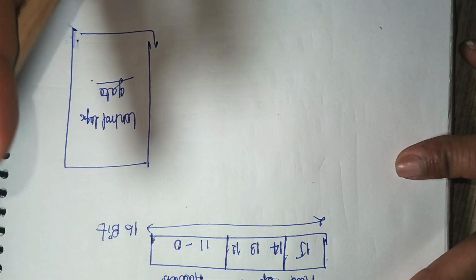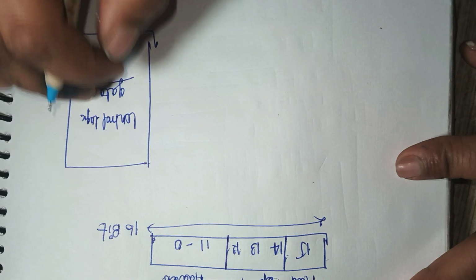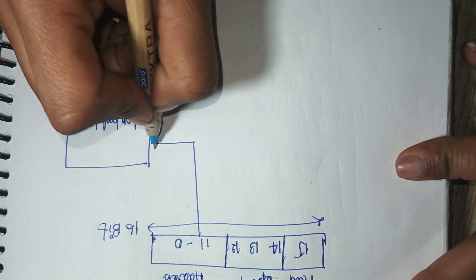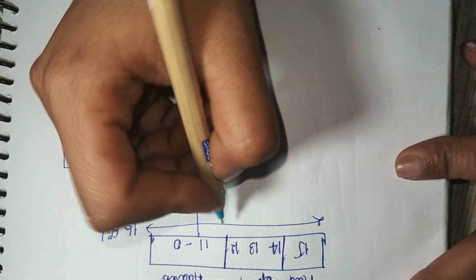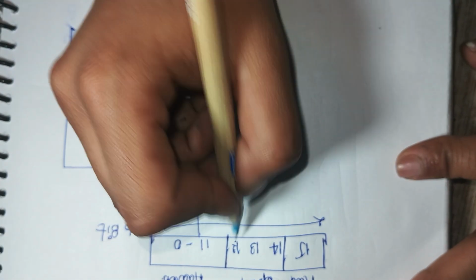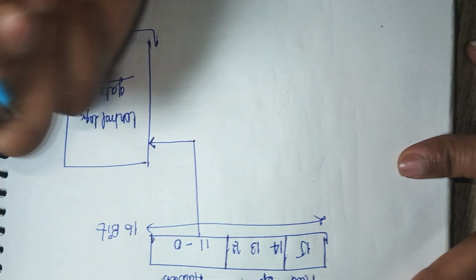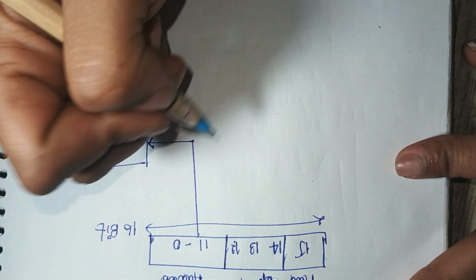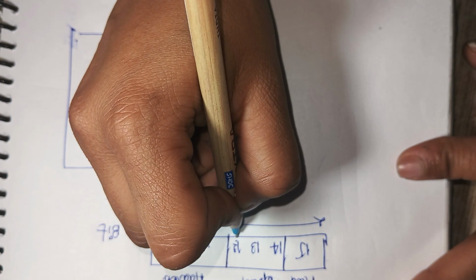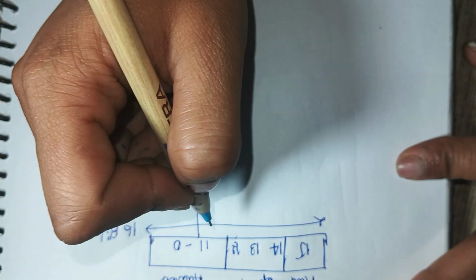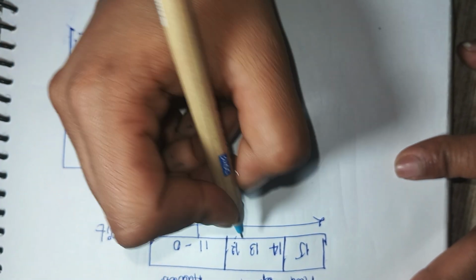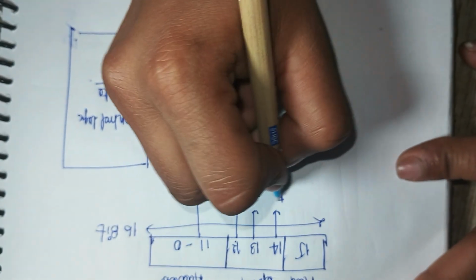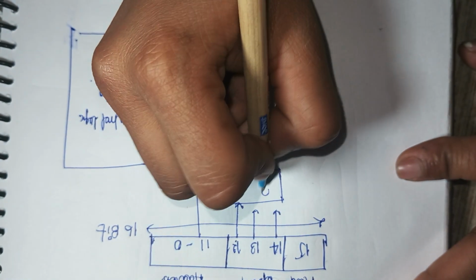Now we are going to discuss the inputs that go to the control logic gate. First is the input from here, the address and the operand, which tells which operation we have to perform, whether it is multiplication, addition, subtraction, or anything. That is, a mathematical or logical operation. Here we use a 3 to 8 decoder.